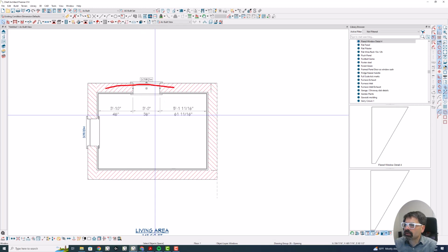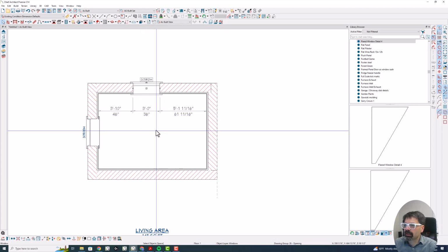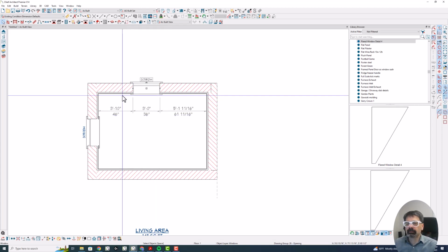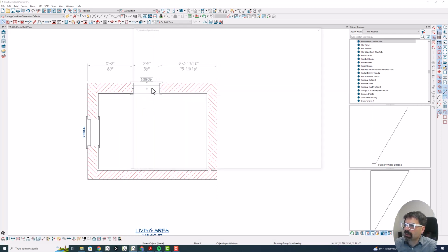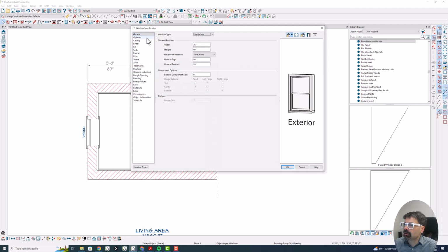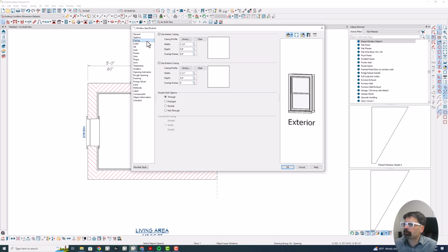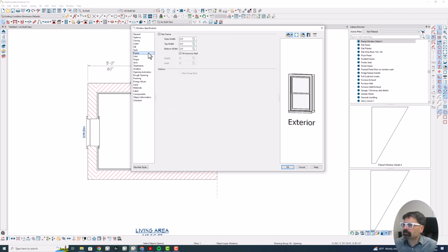Okay, so to start off with, I have a couple of windows. These three walls are that Masonry 12 wall type. I dropped one window in here, and I set in the options that it is not recessed. It doesn't have that option since there's no sheathing layer. It's only just the main layer on the exterior. Casing, you can do a frame that fits to wall.